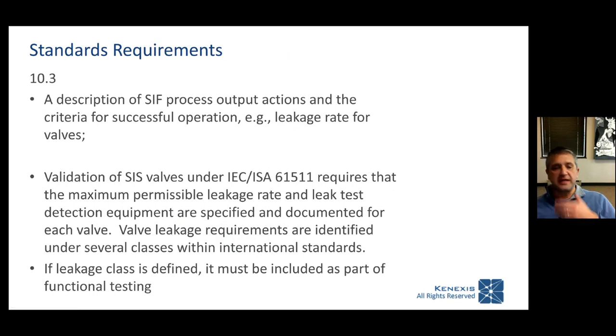Okay, so in terms of standards requirements, the requirement is in clause 10.3. So 10.3 should set off a lot of alarm bells for you. This is the clause in the standard that has that bullet point list of all the things that are required for you to document for a safety instrumented system.